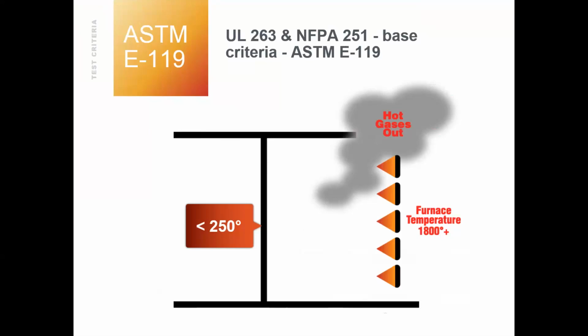So this fabric product is never going to pass ASTM E119. Rolling steel products, never going to pass ASTM E119. And it's just crucial: whenever somebody comes in with a fabric product that carries a 1 hour ASTM E119 rating, it's crucial to ask for testing data and listing reports that indicate that.